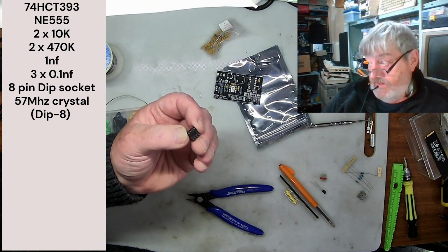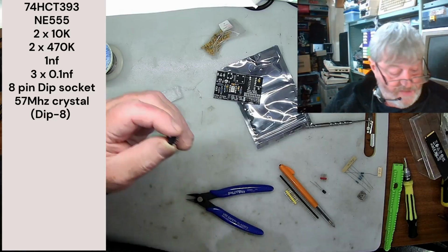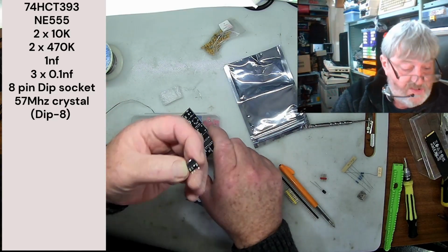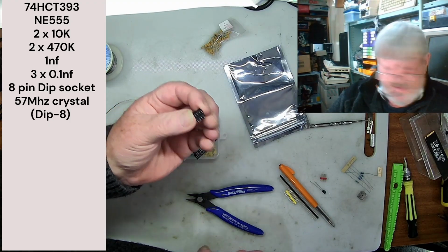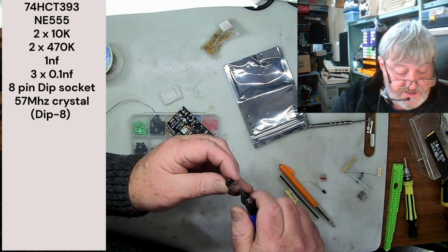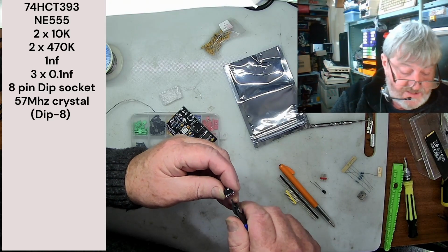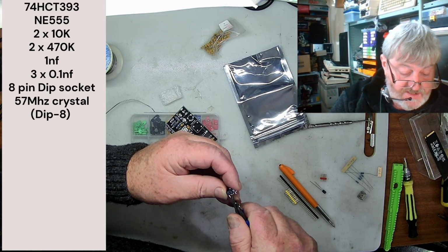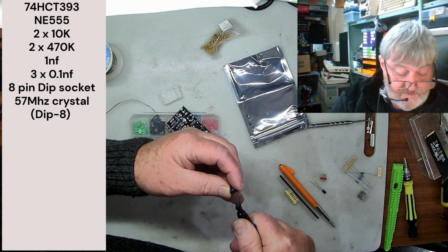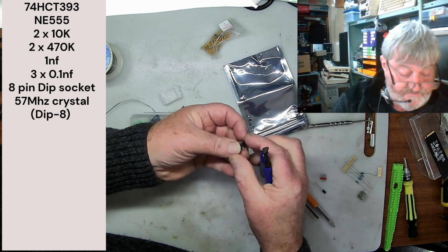Right guys, so I've got an 8-pin IC socket here. Now the problem being is there are only 4 holes on the board, and there's 8 in this. So what you can do, you can get your pair of side cutters, just the 2 center ones on either side, just grab it and just gently push it back into the socket, and they will pop out the other side.